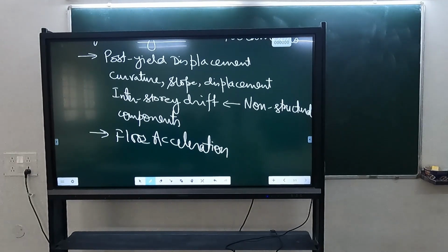But why? The amplitude is not the same. Rather, you mean to say that the amplitude is more at the top. Yes, so the top of the building is vibrating more. The lower stories are having less amplitude, in the same time. So is the time the same? During the same earthquake, this is an interesting issue. I don't know whether we discussed it earlier or not. What do you think, during an earthquake when the building is vibrating, will it be vibrating with the same period?